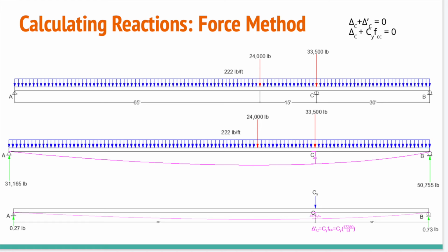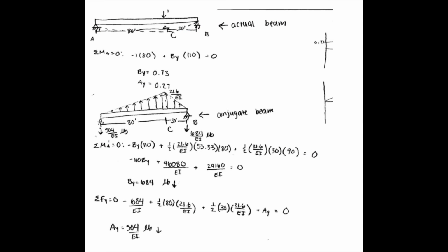Therefore, an influence line was drawn for support C and used to determine that the maximum moment due to the ambulance load occurs when the heaviest part of the ambulance is placed at support C. The reactions at each support were determined using the force method of analysis as outlined below and detailed in the attached hand calculations.